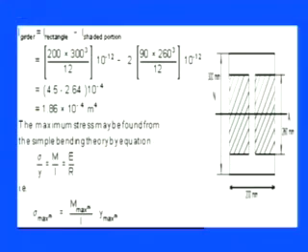So you will be ending up with this kind of structure, and the maximum stress may be found from the simple bending theory equation. As we discussed in the previous case, sigma by y equals M by I equals E by R, or if you want to find the maximum bending stress, it is nothing but the maximum bending moment M by I into y maximum.